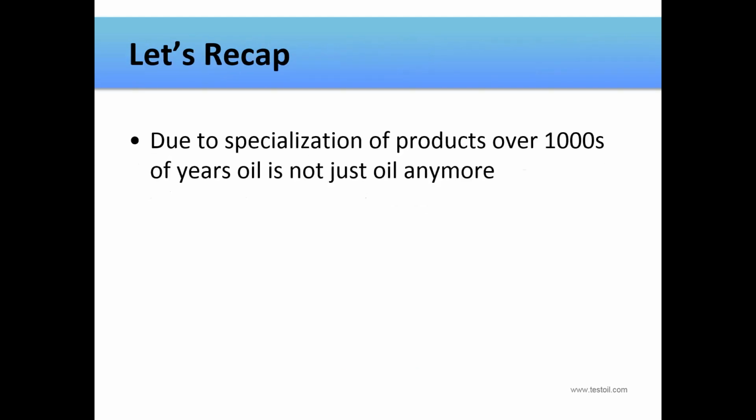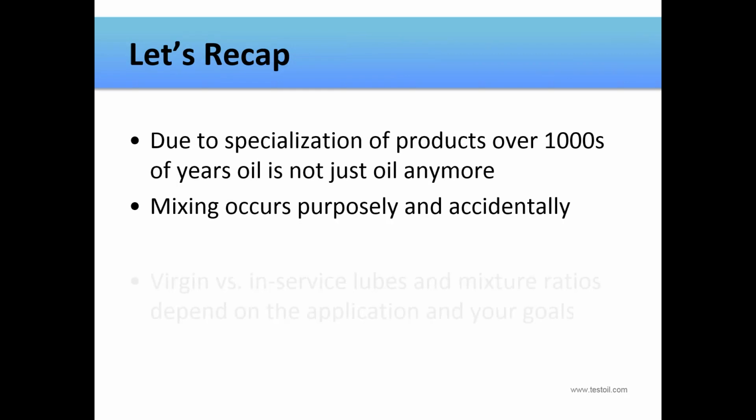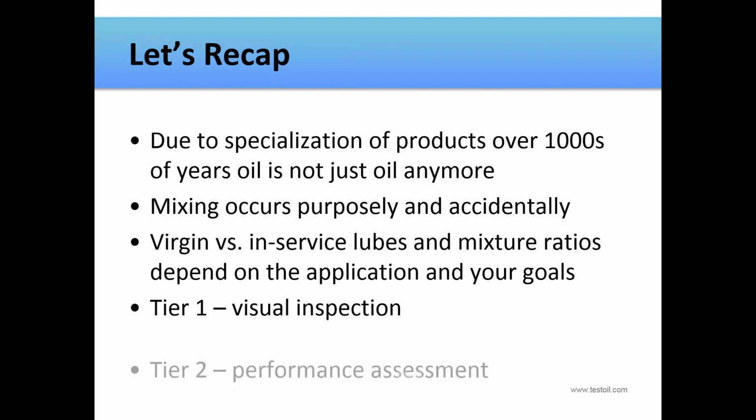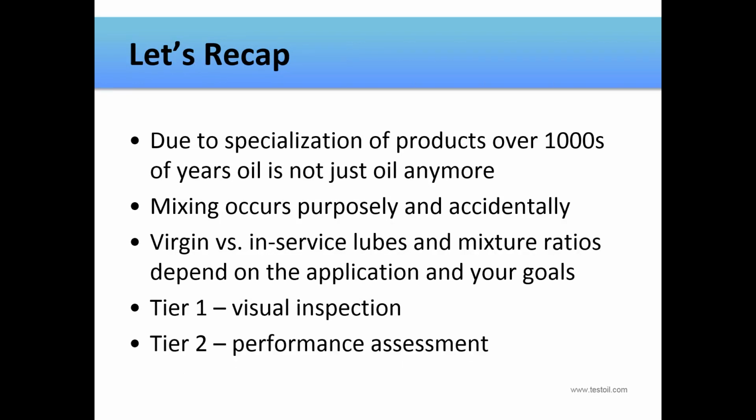So here we'll do a quick recap. And let's remember, it took thousands of years to achieve the specialized lubricants that we know today, and they're still developing new lubricants and increasing performance characteristics. And these specialized additives based on the application in different base oils necessitate that we really understand that oil is no longer just oil. Mixing products can occur purposely and accidentally for various reasons. And as stated, it's better not to mix, but there are sometimes we just have to. And nowadays we are lucky enough that we do have ways to figure out if mixing will be okay.